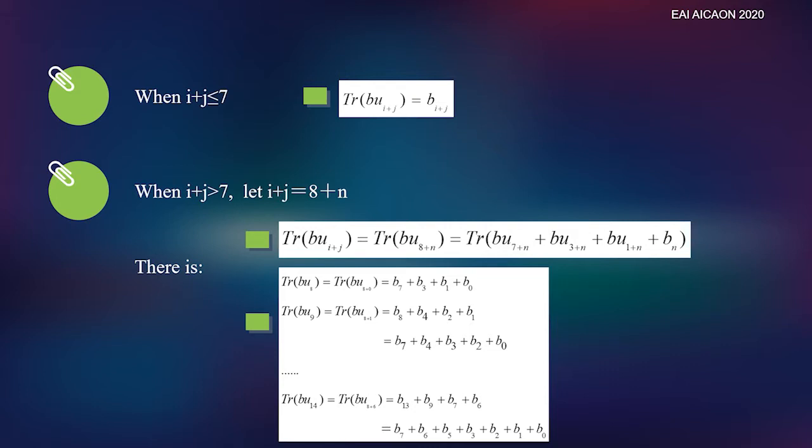It can be seen that in CCSDS Berlekamp representation, there is also an iterative relationship similar to the common polynomial basis representation, which suggests that we can use a similar implementation method to polynomial basis multiplication to design multipliers.